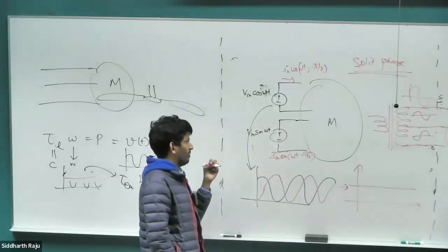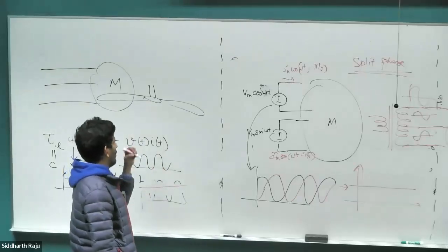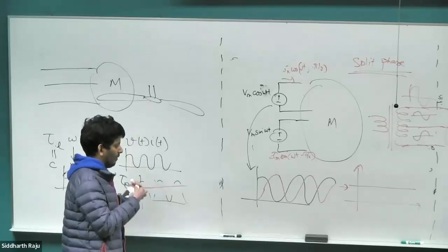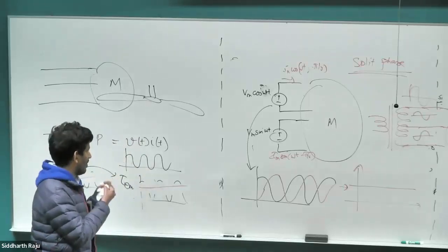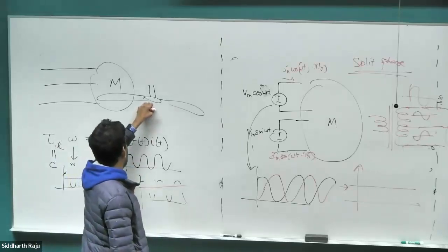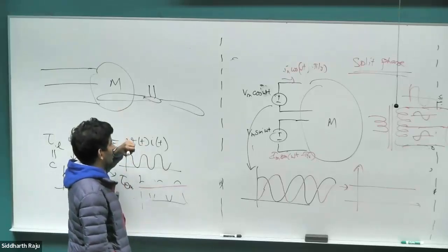So you would have seen a two-phase motor without realizing it's a two-phase motor in a fan. When the fan starts, a single-phase voltage, if you apply it to a fan, it will never start at all. Yeah, we'll look at that tomorrow on Wednesday, why it won't. But what they do is they initially have some kind of additional winding in the fan, which has a capacitor in series with it.